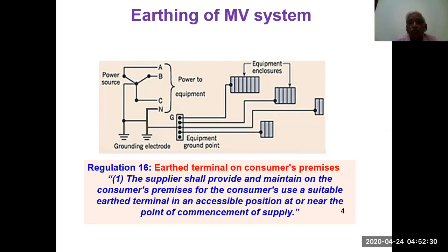Customer has to make his own extension and he can provide another grounding on the load side and connect it to the same ground bus. So it is a separate ground bus. They are not interconnected. Every conductor is going from the ground bus itself. The advantage is, in case there is a problem anywhere, the entire ground bus voltage changes, but there is no change from equipment to equipment, as happens if you connect them in series or loop them, as is the practice.